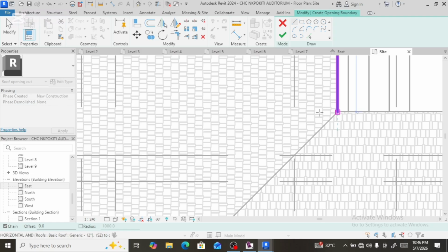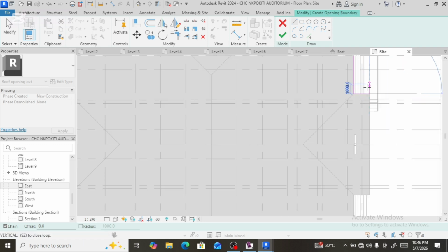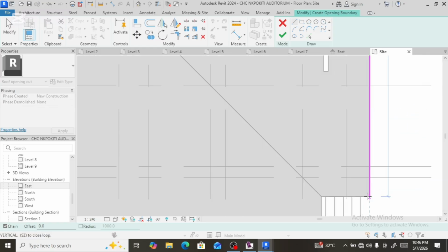If you don't know how to do a gable roof per se, you just pick your lines in the roof sheets by footprint. Then, for the particular slope you don't want to exist, you highlight it and define that slope.